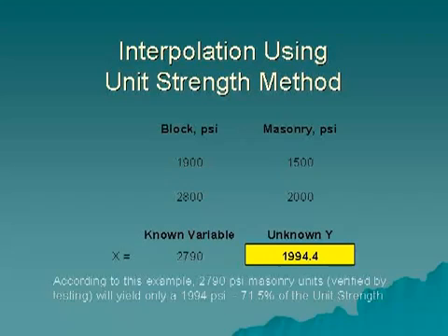By using interpolation of the unit strength table, we see the engineer must design the masonry using just 1,994 psi F'm, or at the very least, the design does meet the 1,500 psi F'm typically needed for structural purposes. In this example, is the value of higher strength masonry appreciated or quantified? Let's consider the alternative prism strength method.